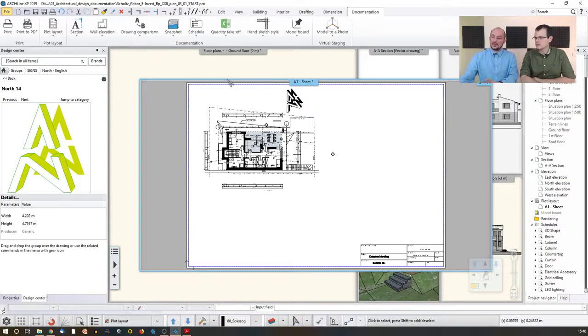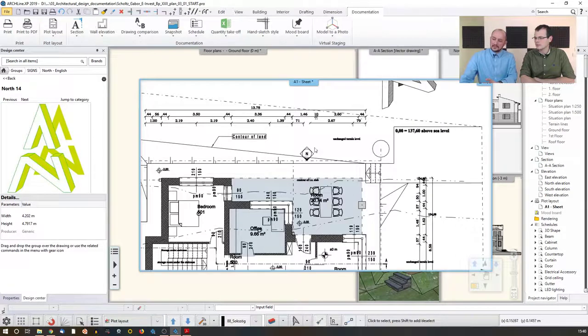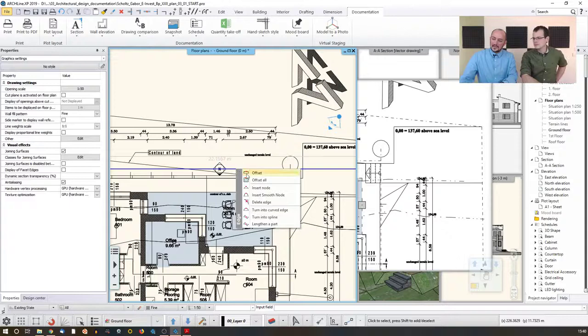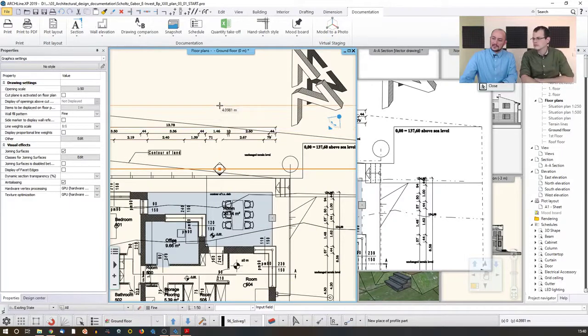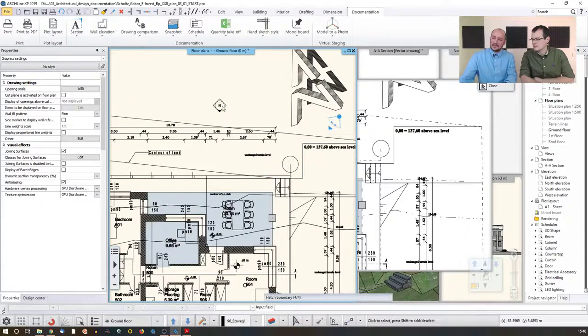Let me just quickly show you an example of that. For example, I don't like how this symbol is organized here. It's overlapping other things. It's not clear. So I'm going back to the original drawing. I'm just shifting it, and I just use an offset, and I just place it someplace here. It's much better there. Let's just reorganize that, and then now it appears over there.